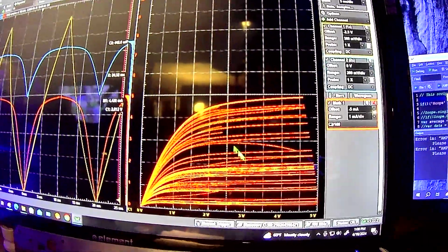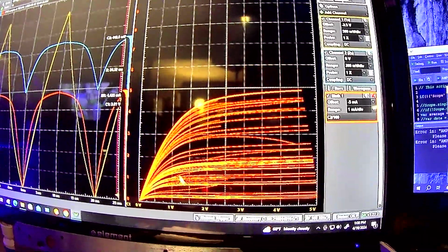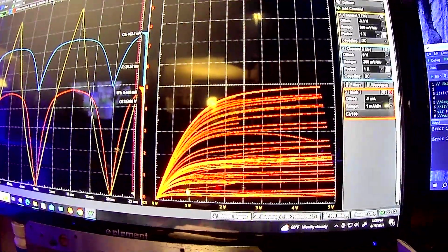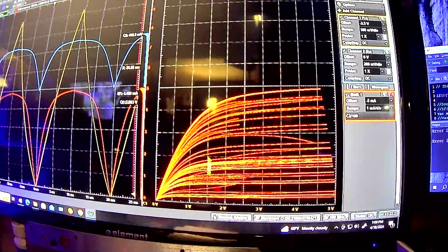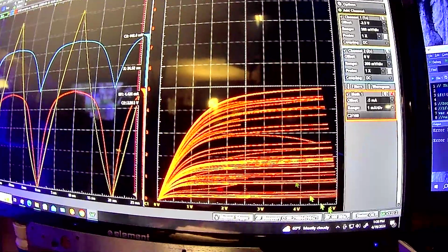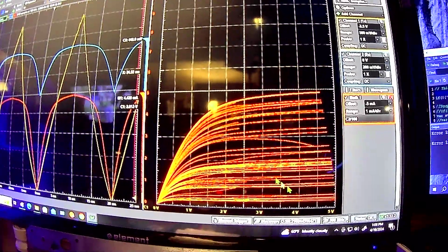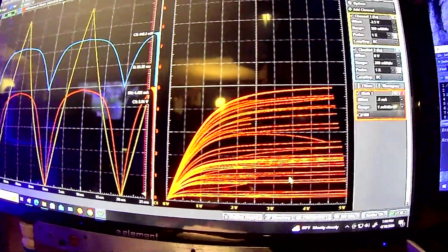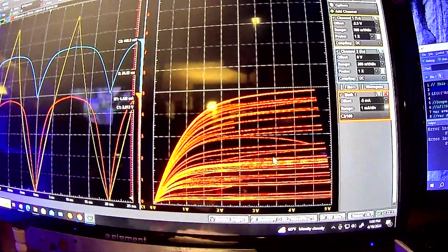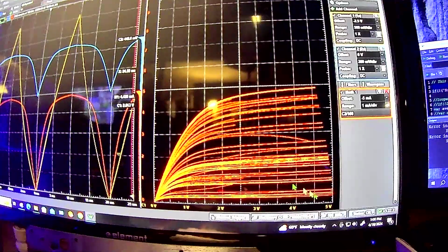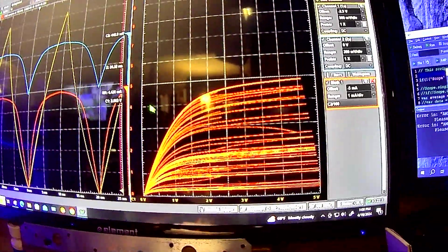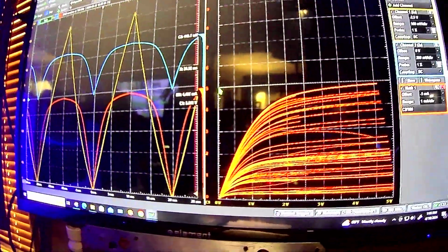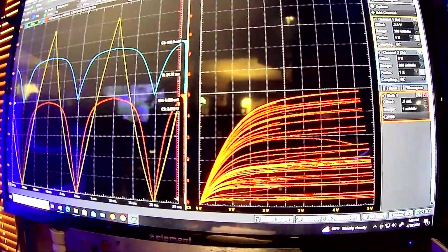But at any rate, it still allows you to see where this thing behaves more like a voltage controlled resistor, as opposed to an amplifier, because it's going to mostly operate like an amplifier over in this region. So that suggests what you might want to aim for, because if you drew a load line through this thing, and let's say its saturation would be right up here at 5 milliamps, right?